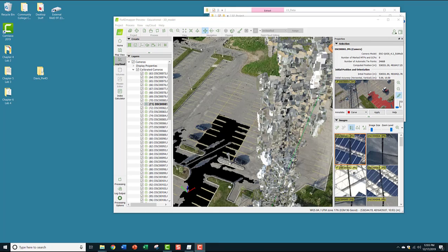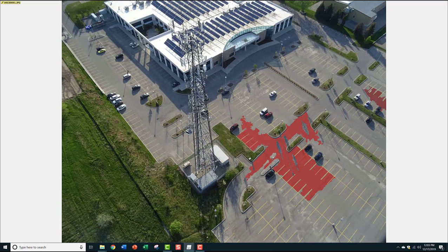So when we hover the mouse over the image in the selection window, you hit the space bar and it comes up full. This will enable the full extent of your image. Now, of course, to exit it, you just hit the space bar again. But now notice that your mouse pointer resembles a pencil. What is happening is that chunks are larger or smaller depending on how homogeneous the pixels are. The more homogeneous, the larger the chunks of pixels, and vice versa. The chunk size will also be based on zoom scale. The closer you zoom in, the smaller the chunks get.